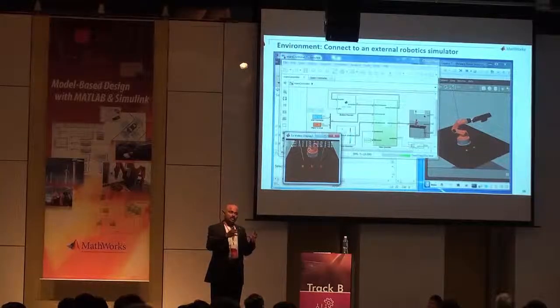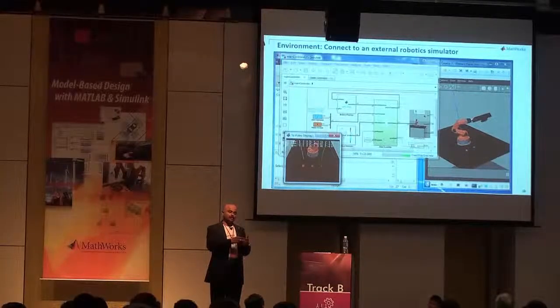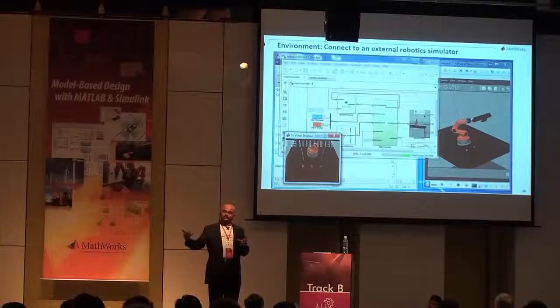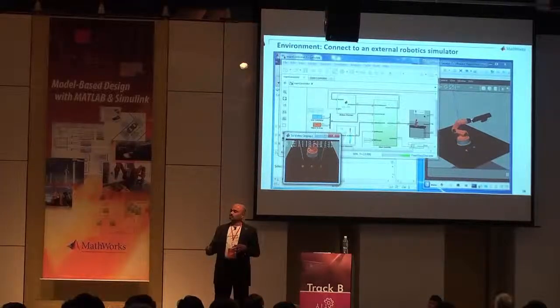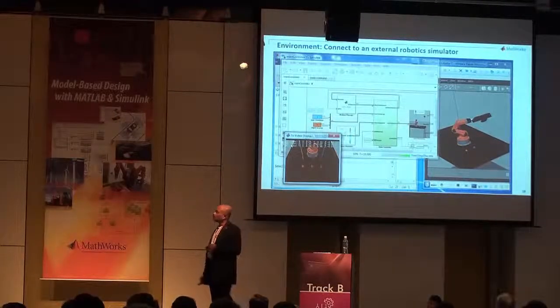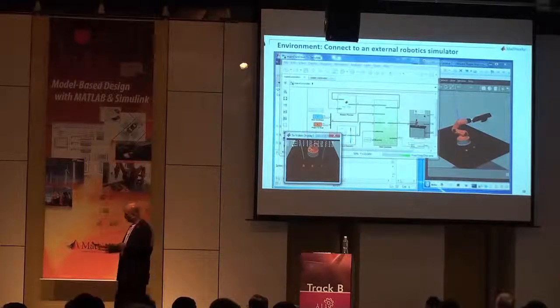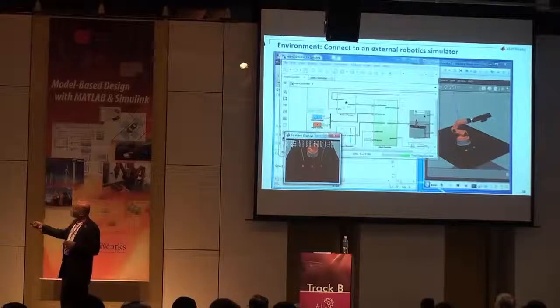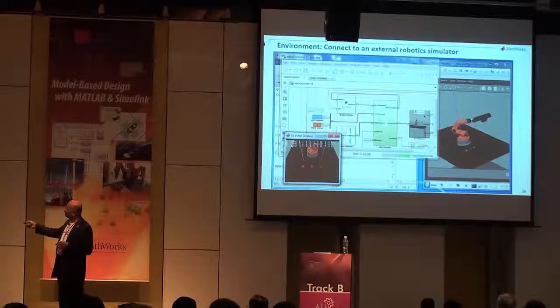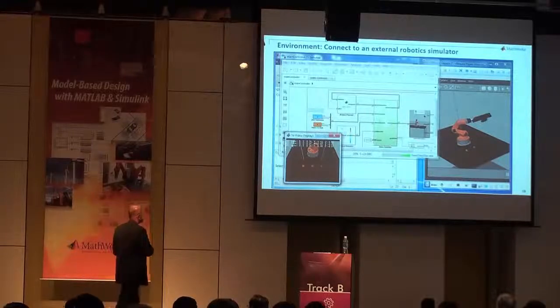So you can have your dynamics model inside of MATLAB and Simulink. You can interface it to Gazebo to do the visualization of how the robot works. So here, what you'll see is this is the MATLAB Simulink model of the controller, and then the visualization gets done in Gazebo.